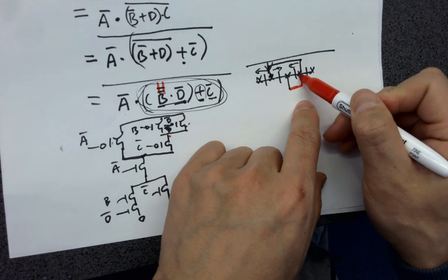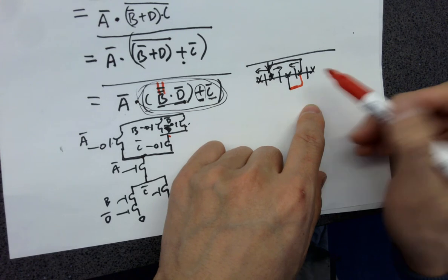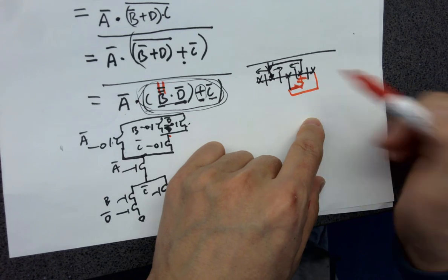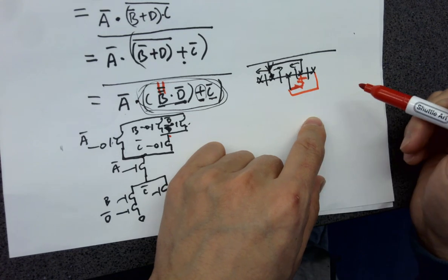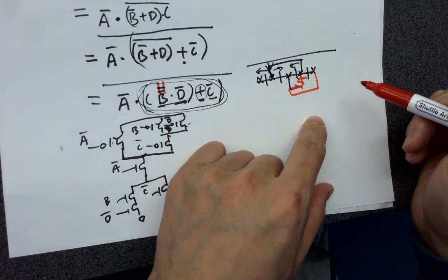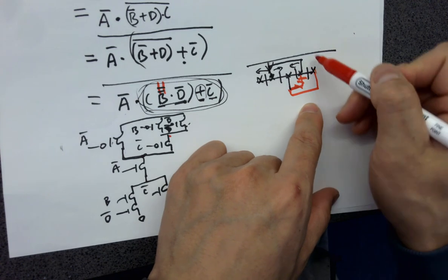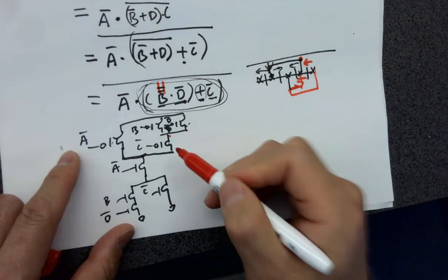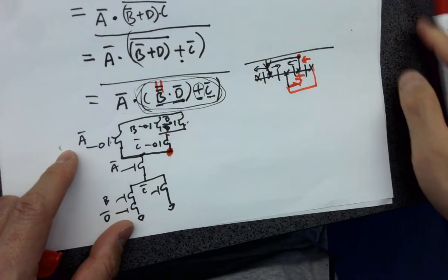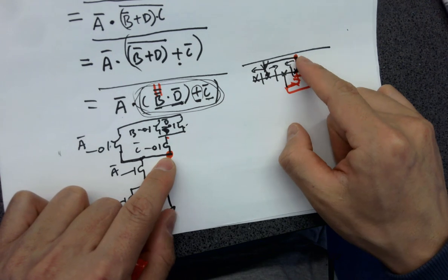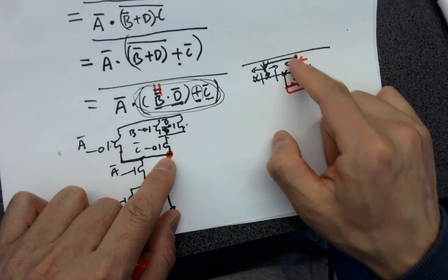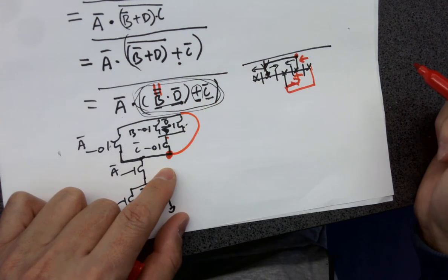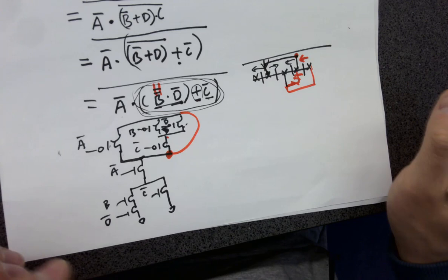You are shorting the 2 nodes of this transistor, so it doesn't work. What's going to happen? If you short it here, you are trying to flow the current that way, and you are treating this node as this node. But it's not. This node is VDD. So you are basically shorting this one to VDD. It doesn't work.